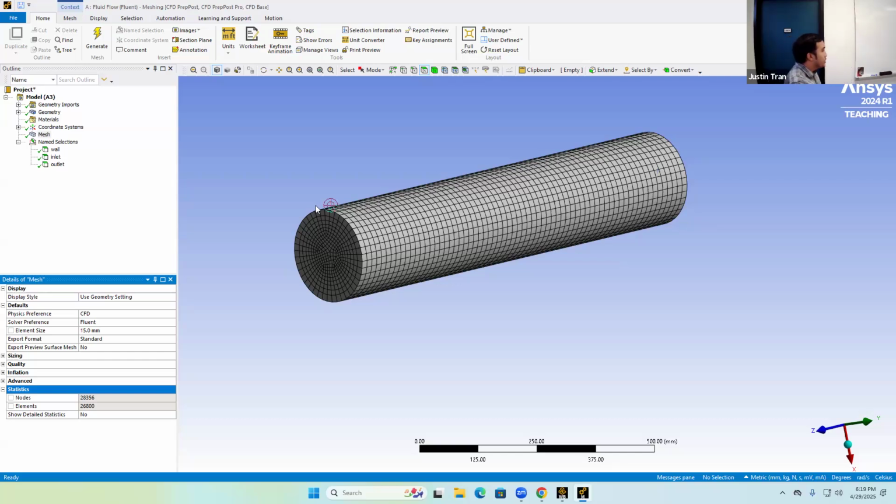One thing about fluid simulations is that you typically need more elements for your fluid simulation than your solid one. And so don't be afraid to push the element count. One thing that's interesting about Fluent and ANSYS is that the element limit for the student version is actually higher. I don't know exactly what the element count is, but I know for structural simulations, the limit is maybe about 64,000 elements.